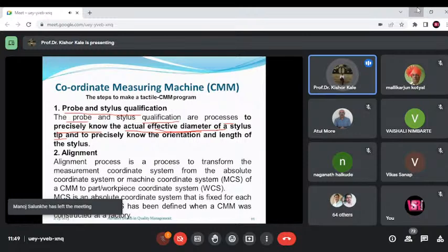Now, this is the rest of the part which we will be discussing. This would be the same in the case of CMM as well as in the case of laser. This is called the computer-aided tolerance verification process. Now, we have the 3D CAD model, that means this ideal model is there with us. The acquired 3D data, whether by CMM or by the scanner, would be there. They will be computationally aligned properly to each other. Then verification between the two would be done, and then deviation will be shown.